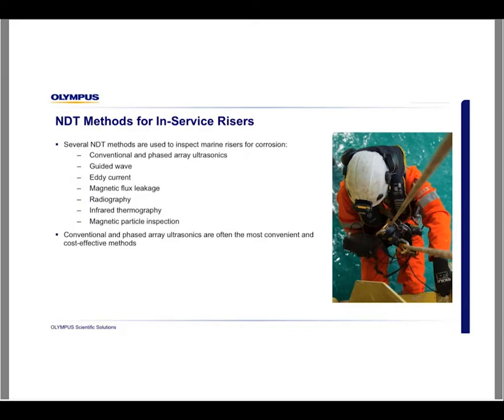Now, there are a number of NDT methods that are commonly used for in-service risers, in particular to inspect for corrosion. One of the most common and well-known are conventional and phased array ultrasonics, but there are also other techniques such as guided wave ultrasonics, eddy current and eddy current array inspections, magnetic flux leakage, radiography, infrared thermography, and magnetic particle inspection. And there are costs and benefits to each of these techniques. However, conventional and phased array ultrasonics are often the most convenient and the most cost-effective methods of all these.